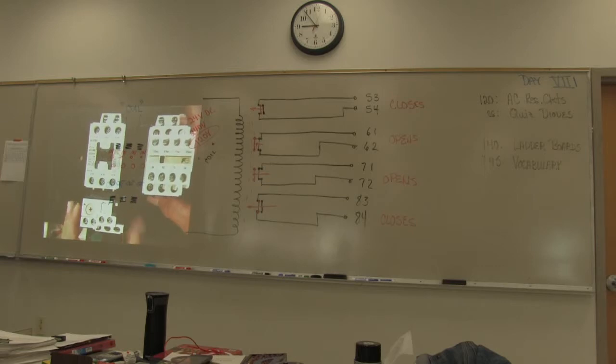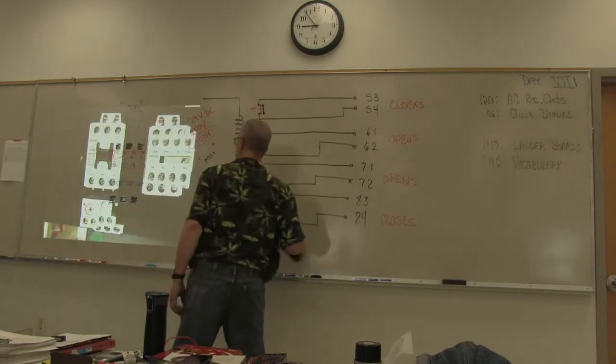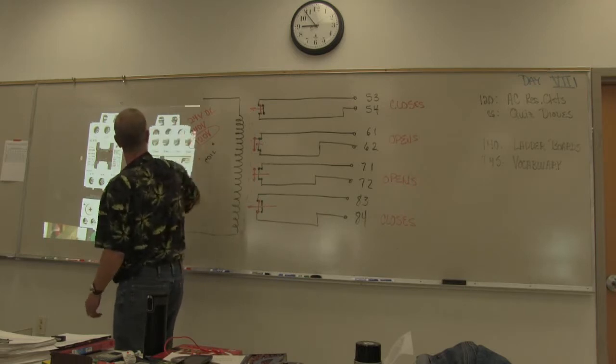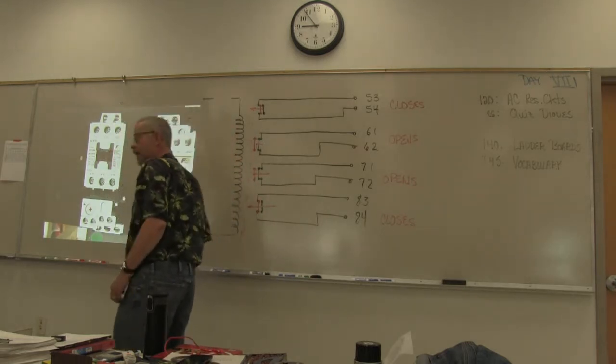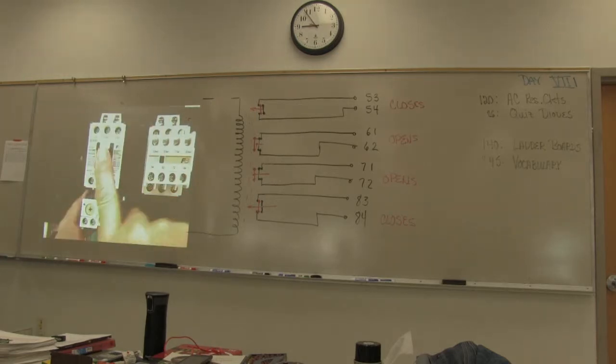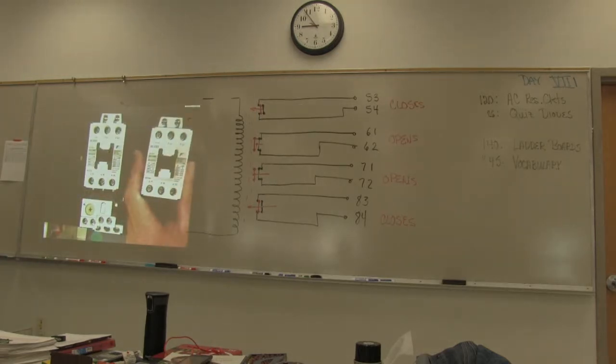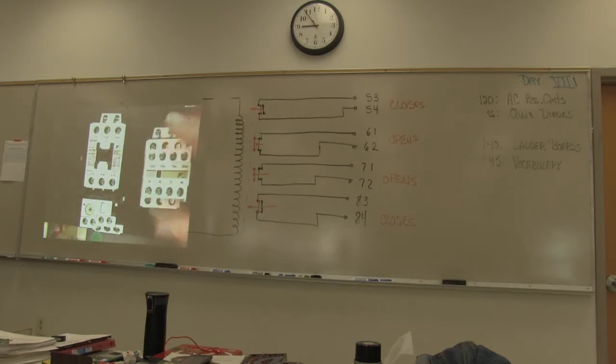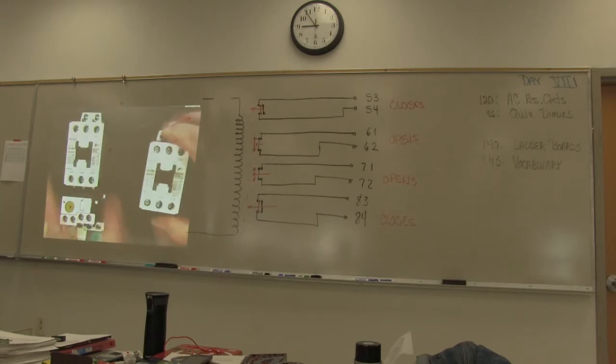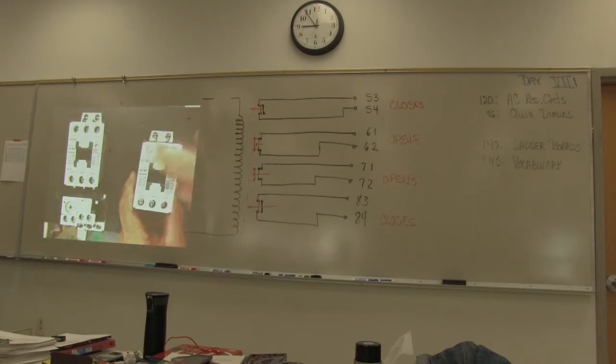Okay, here is the motor setup. Okay, all this is, if you look at this here, this is just the same as that with this piece removed. So it's exactly the same contactor that we're using. This piece that we put on this contactor is an expansion module, because the contactor itself only has normally open. All of these are normally open. So what we do is we connect into the coil, which is this push button here, and that reaches into the back and pulls on this, so we can multiply and change the configuration of the contactors.